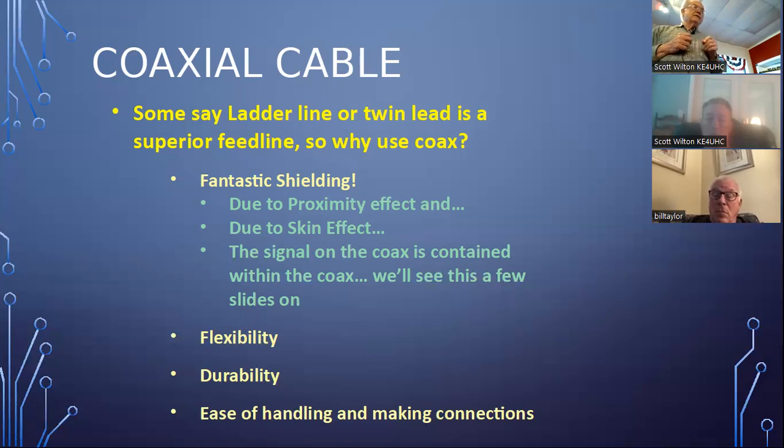Talking about twin lead now. Twin lead, yes. And you can't bend it the hard way. This way. You can only go this way. So you have to make a twist and then go like that to make a transition, and that causes problems with it. So it's great for a straight line. It's great if you don't worry about field.